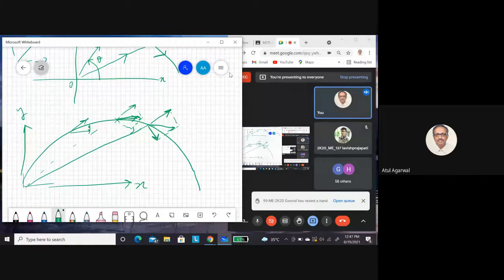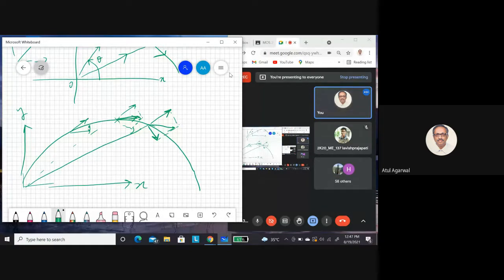Okay. So how many different ways have I represented my velocity? Number one, in xy components. Number two, in path coordinates, where it is just tangential velocity. These are my path coordinates, ET and EN. Then my r theta coordinates. If I take the r coordinate like this and theta like this, I get unit vectors ER and E theta. You get it? Yes, sir.